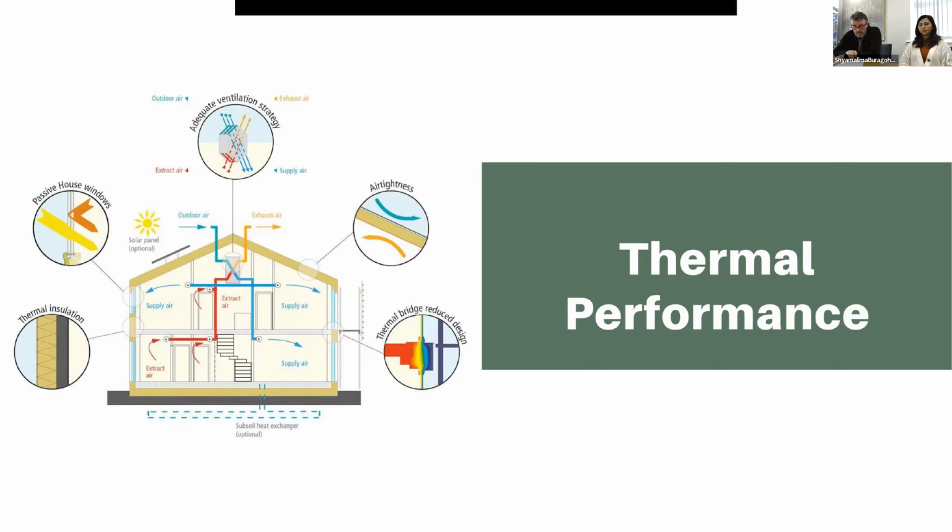In warm climates, you'll be trying to cool the building and stop the heat getting in, and the reverse in temperate climates. Air tightness and air infiltration needs to be controlled, so that you don't lose your heating and cooling through infiltration. Depending on the outside wind pressure will test the leaks in the building more so. When you talk about air tightness, you have to be very conscious of ventilation within the building and healthy environments in the building, and air quality. And we'll talk a little bit more about controlled ventilation later.